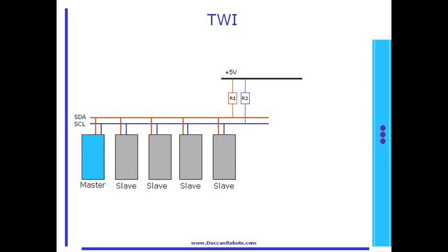The task accomplished by TWI and by using an 8255 chip has no big difference. Finally, in both cases, the microcontroller interfaces with other peripheral chips. But there is a major difference from a design point of view. Using TWI, you save space in complex PCB designs. You can add extra devices to the same bus of SDA and SCL anytime. Your application also becomes simple to write.